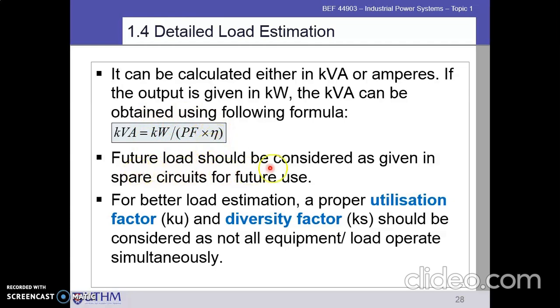Future load should be considered, as given in spare circuits for future use. For better load estimation, a proper utilization factor and diversity factor should be considered, as not all equipment or loads operate simultaneously.